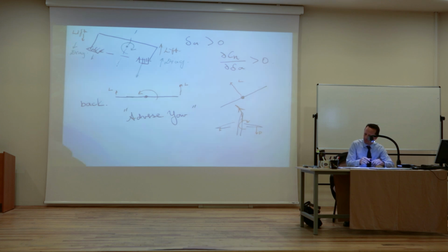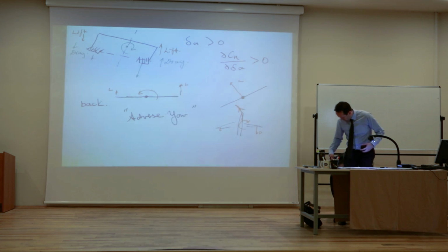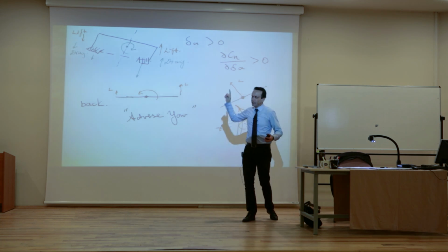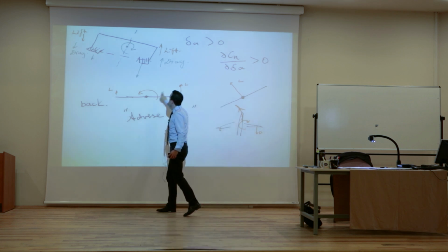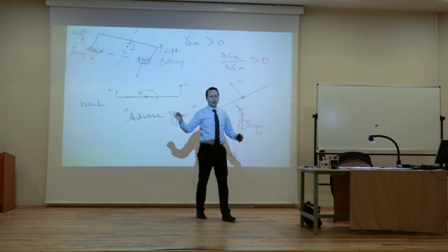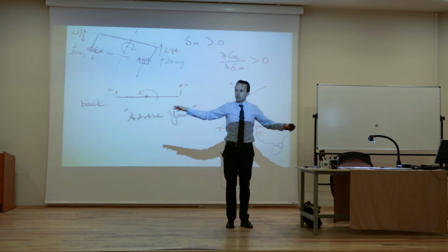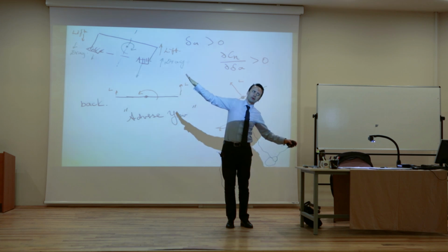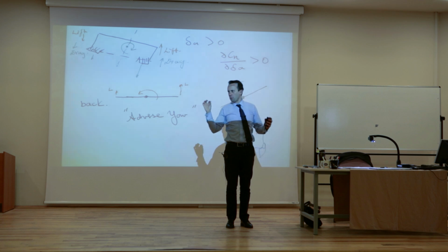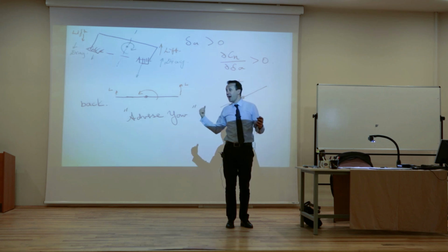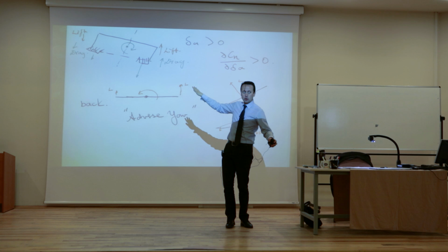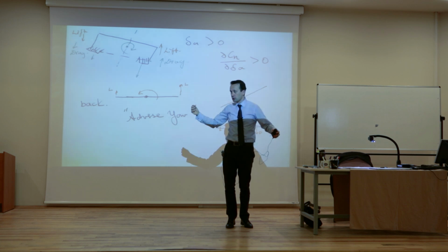Yaw in the wrong direction. Now, this is not really a problem if that drag difference is not too big, which means if the difference between these two lifts is small. If the lift difference is small, which means the airplane is slowly doing this, then the difference in drag will also be small, right? And the adverse yaw will be small.